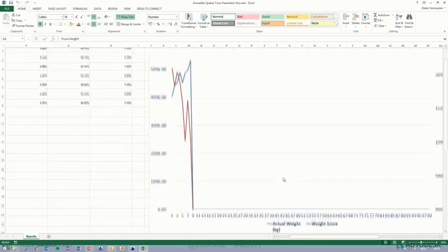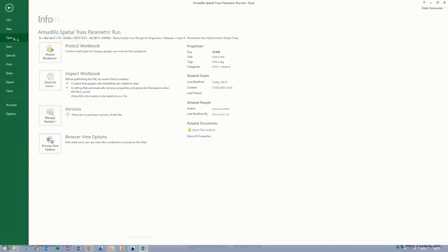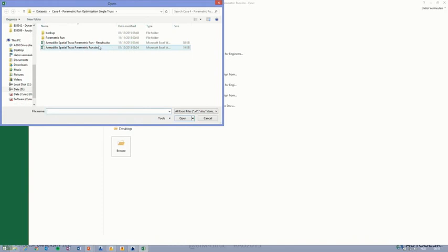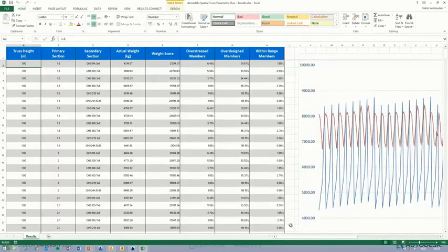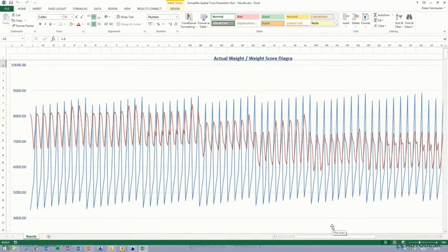So let's bring those 2 guys next to each other so that you can see the process in the robot. Run. See, the model is changing. The loads in this case are not changing. It's all the time the same loads. But now it's doing it for a different width. It will use another height in a few seconds. It also changed the member types, so the section types, I mean. Well, you cannot see it very visually in here because the sections are close to each other. There it goes.